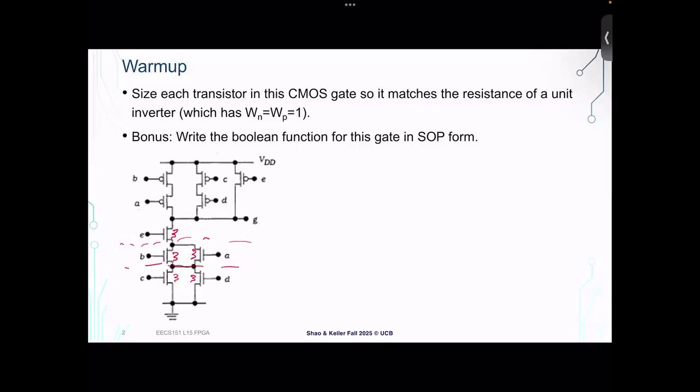Okay, so that was NMOS. Let's talk about PMOS. PMOS has 3 paths in parallel, right? But we basically just said parallel doesn't really count for sizing because we can only guarantee that one of those paths is going to be on at any given time.